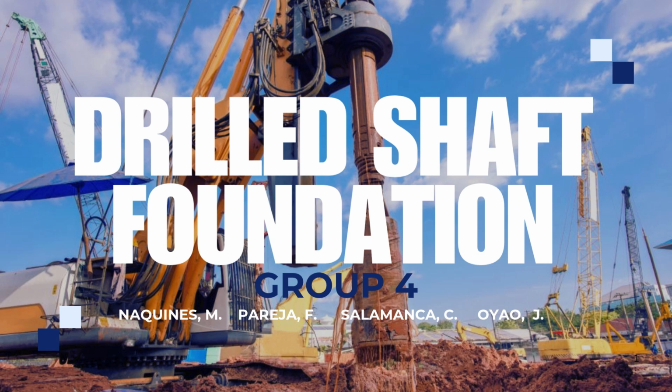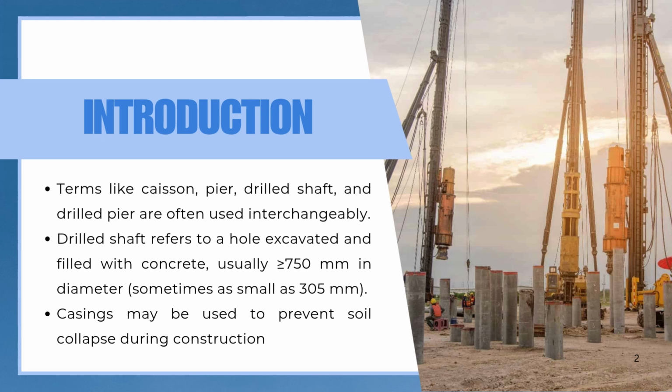One of the most widely used deep foundations is a drilled shaft foundation, also known as caissons, piers, or drilled piers. Drilled shafts are constructed by excavating a hole into the ground and filling it with concrete, and often with reinforcement. These foundations are typically 750 mm or more in diameter and are commonly used in bridges, buildings, and heavy structures, especially in areas with weak or variable soil conditions.